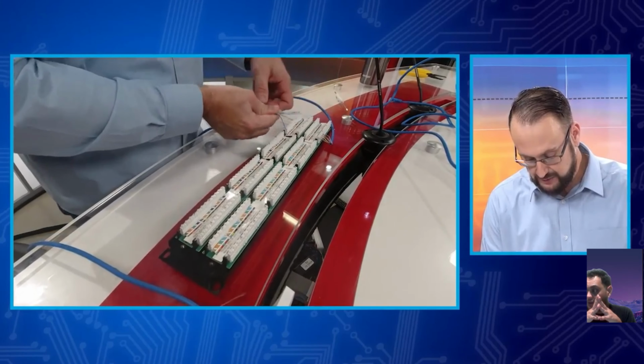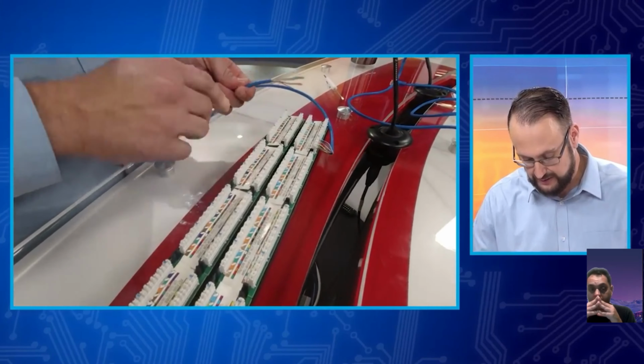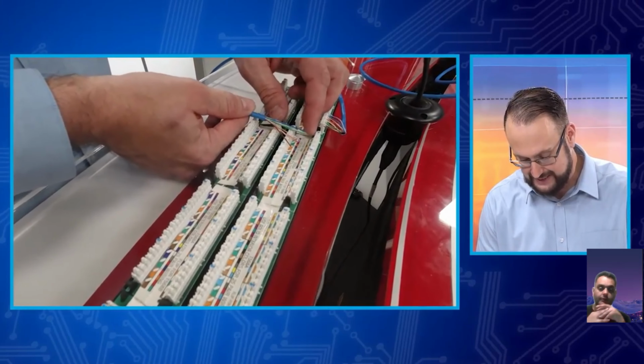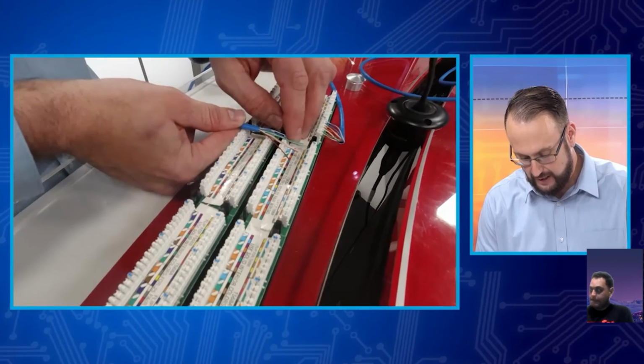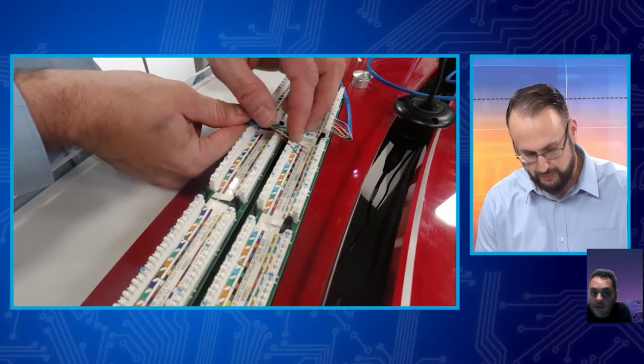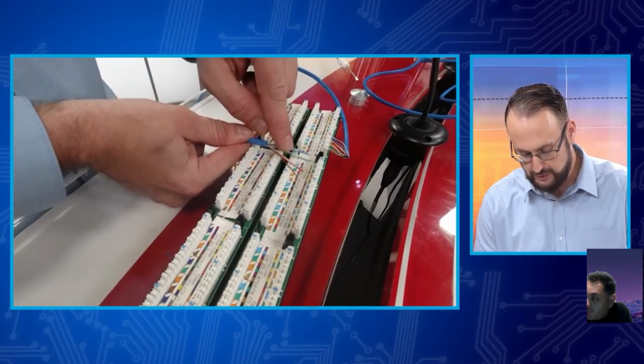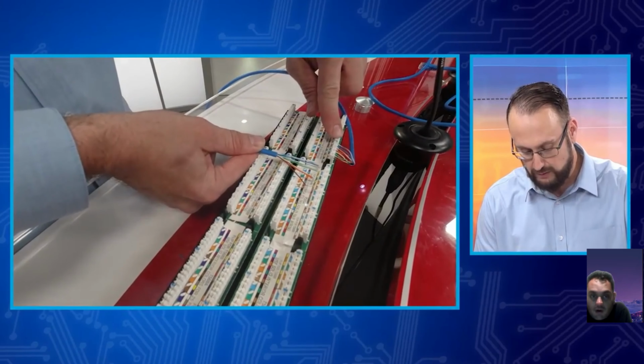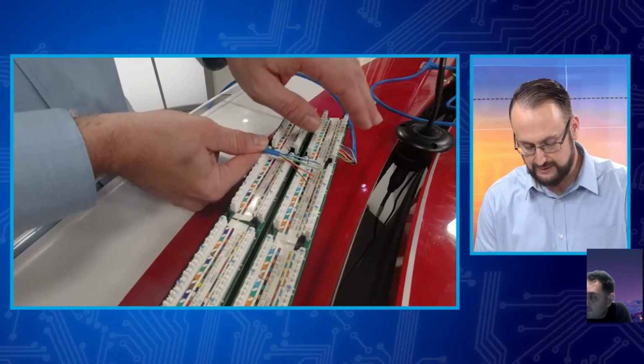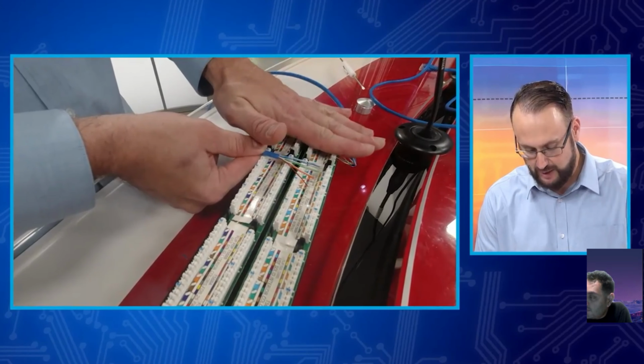What we need to do is take these, and you can see that there is an arrangement here, and they let you know exactly how these have to get punched down with your punch down tool. Once you punch them in the right order, like we've already done here, we've got the patch panel itself wired.